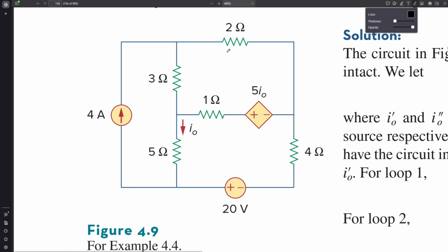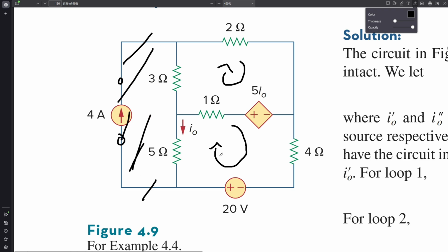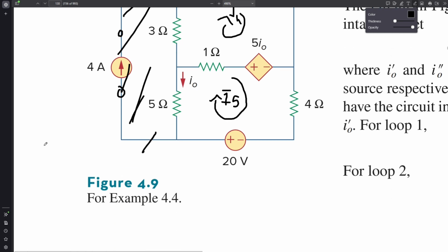The equation for the second loop will be when you open the circuit around the current source. So now that will be two loops, one here, because everything else will just be removed over here. Now, because we already used I1, I2, and I3, so we don't confuse ourselves, just make this I4 and make this I5. Okay, so now the loop for I4, let's call it loop 4.